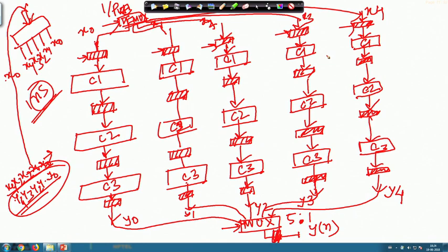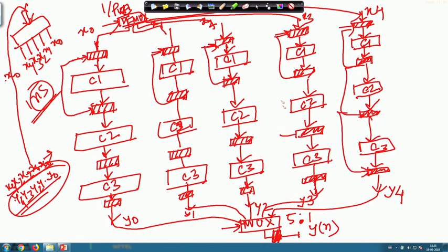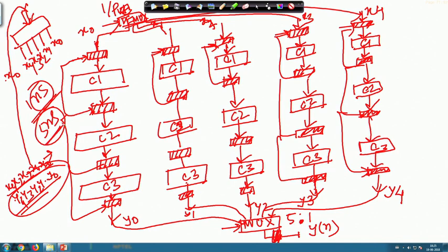The internal will be different. And they are all connected to the same clock, and this clock will be 5 nanosecond, which is the requirement of the processing elements' critical path, the clock requirement for the registers. So that will be 5 nanosecond.